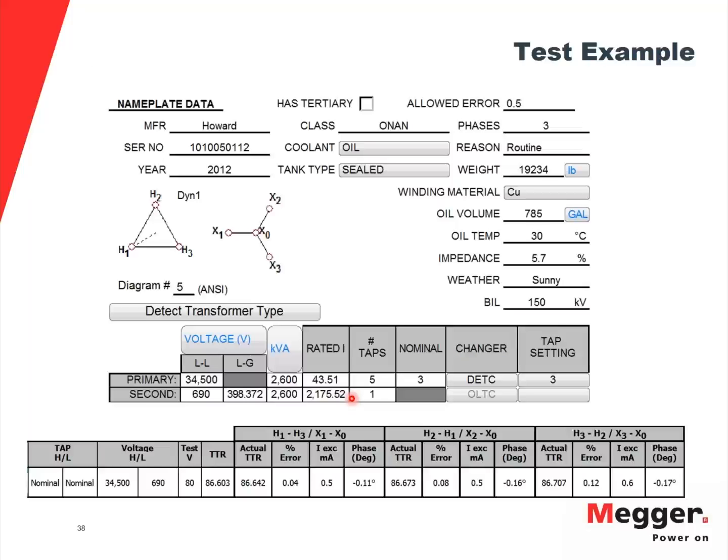Yes, thank you, Dinesh. And I'll add one more point: when you're getting to that lower resistance, your connections make a big difference as well. If you're using those grounding studs or the little plug-in connections, and you're hooking to one spot of it, or if you're up even an inch or two higher on a different side, that could influence the resistance as well, because the resistance of that connection will add to it. But yeah, that was a good point. Thank you. Robert, your point was very valid. You are correct that even changing the connection a little bit can affect your reading. So that's a very good, valid point.